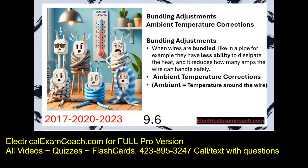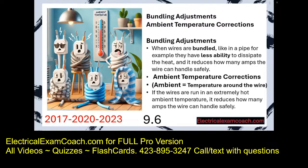Ambient temperature corrections are like this. If wires are run in an extremely hot ambient temperature, it reduces how many amps the wire can handle safely. And let's not forget the basic definition of ampacity. It's how many amps the wire can handle safely under its conditions of use.